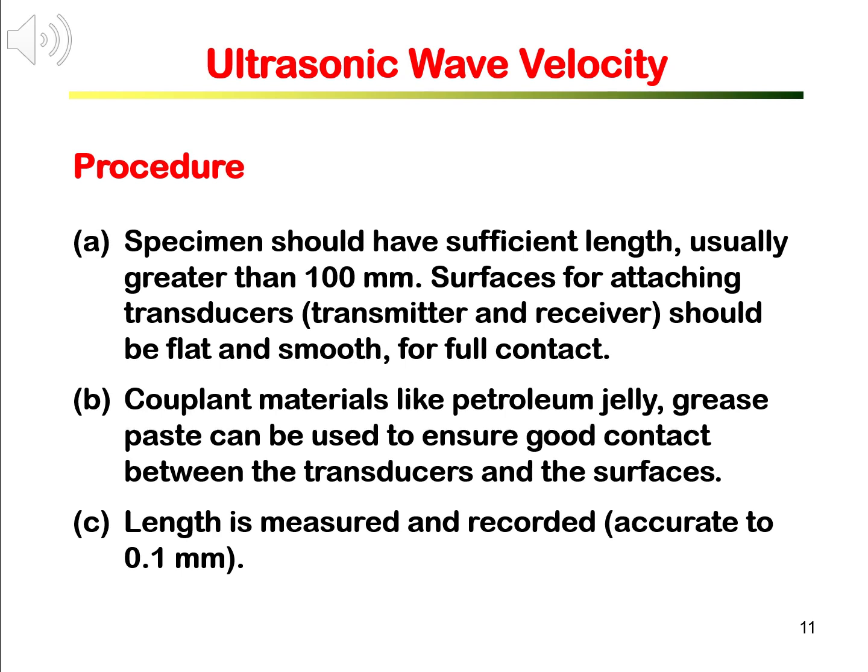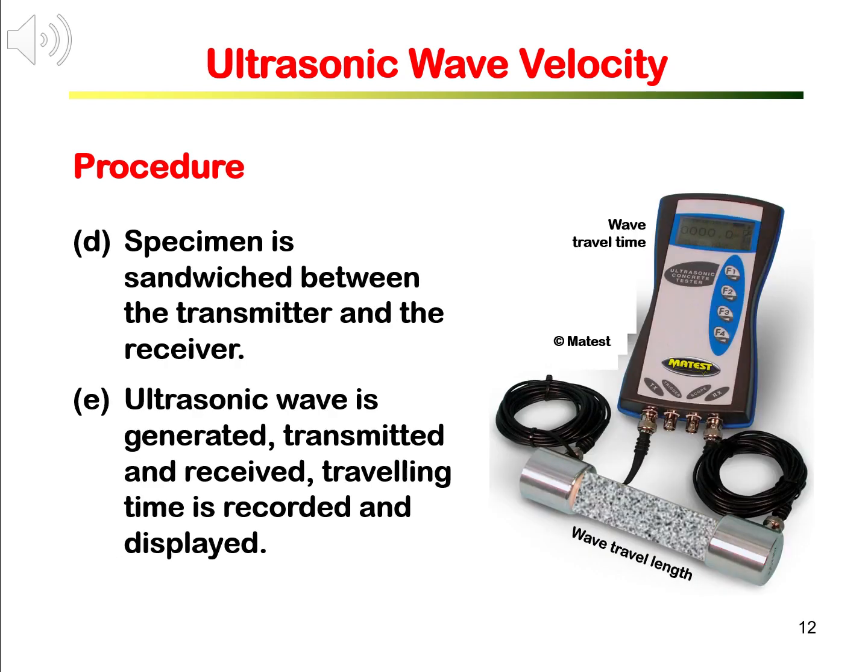Specimen length is measured and recorded to the accuracy of 0.1 mm. Then the specimen is sandwiched between the transmitter and the receiver, as shown on the illustration.